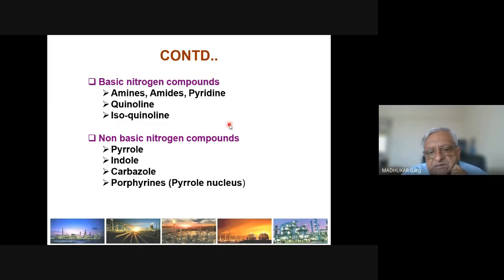Okay, so these are the kind of nitrogen compounds, and they also get removed once you go through a hydrogen treating step of any of these streams. They actually form ammonia when they react with hydrogen, and that's how we remove these nitrogen compounds.